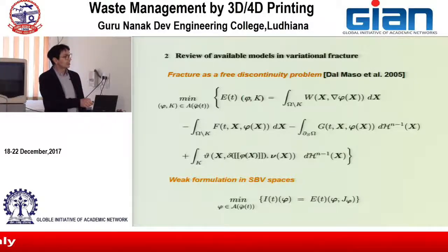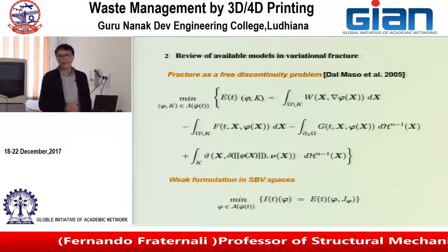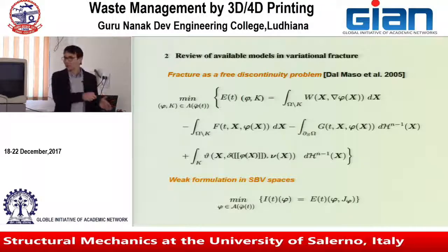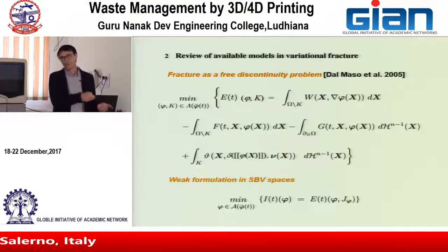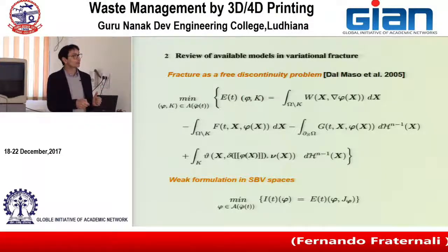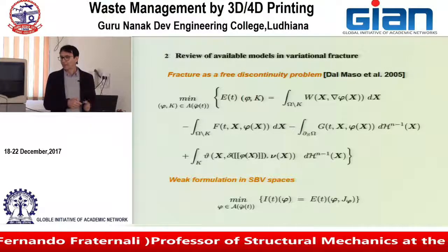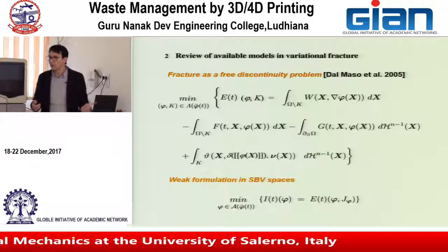This is the fracture energy density per unit surface. So we are minimizing an energy which is composed, let's drop these two terms for simplicity, of a bulk term and a surface term, if we are in 3D. And those two terms compete with each other. And we want to minimize this energy, so the fracture occurs.